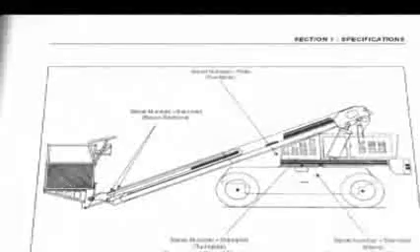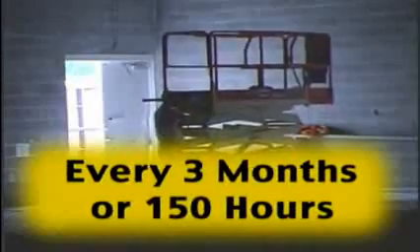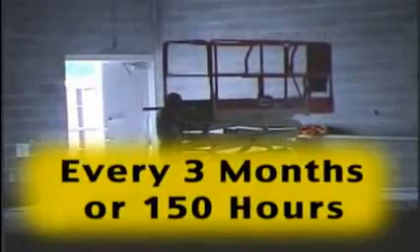Weather conditions must be considered before using any lift. Additional inspections may be required by the manufacturer. These usually are to be performed every 3 months or 150 hours of operation, whichever comes first. These inspections should only be done by a licensed professional.